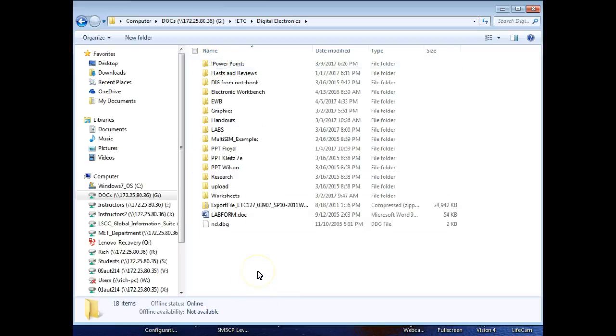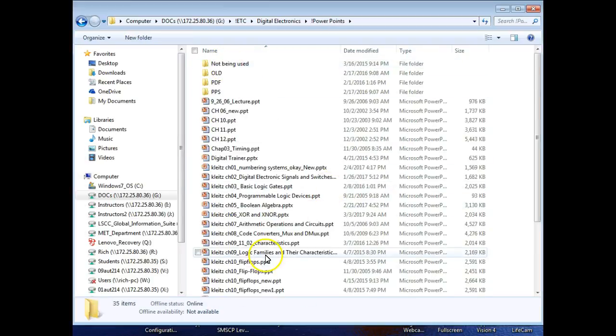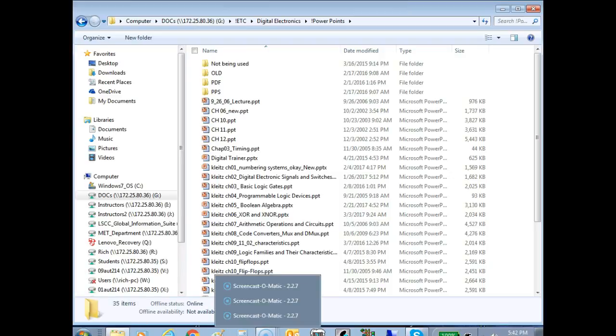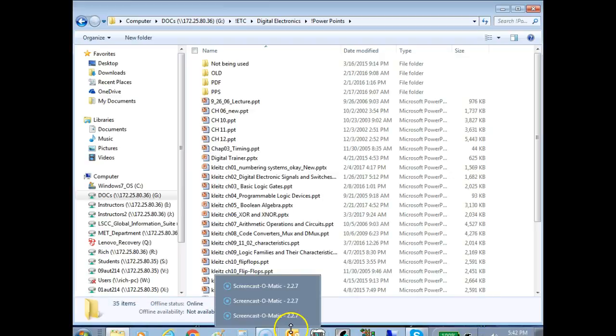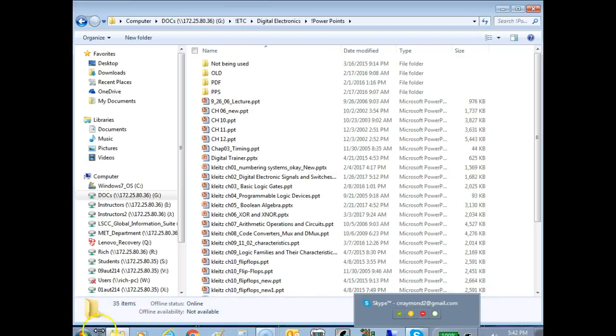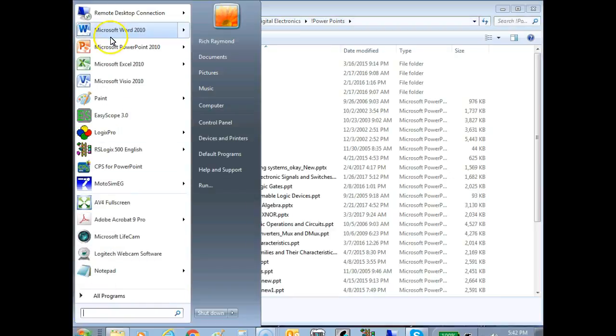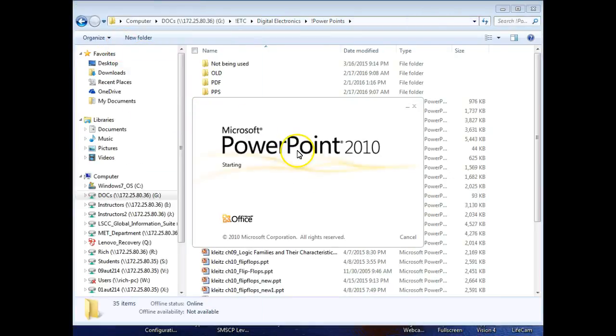So we looked at a 7-segment display, right? And we talked about the 7-segment display. Yeah, and we have two types, if you remember right. We have a common anode and a common cathode. So the 7447 is a common anode driver. So what that means is inside the 7-segment display, all the LEDs are connected together, but the anodes are connected together, right?